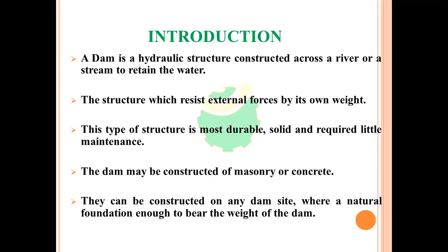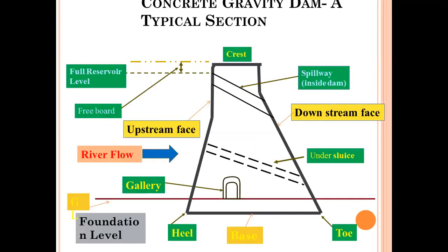The most suitable sites for the gravity dams are hard rock areas with less lineaments, that means with less cracks, fissures, folds, faults. A very strong basement is required. So, we must prefer igneous and metamorphic rocks for construction of these gravity dams.